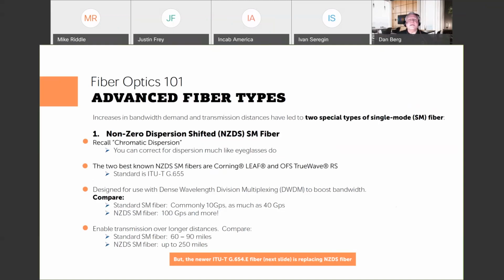And what 4-wave mixing is, is when there are several light wavelengths together. Several lasers can fire into this optical fiber at the same time in different wavelengths. What they found is that when, say, 3 wavelengths move down the optical fiber, they would interfere with each other and create a 4th wave, which would cause errors in the communication system. So they designed this fiber specifically to overcome those issues.